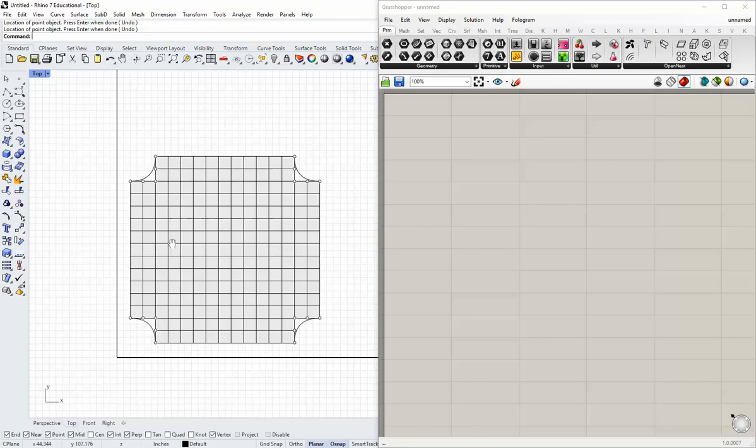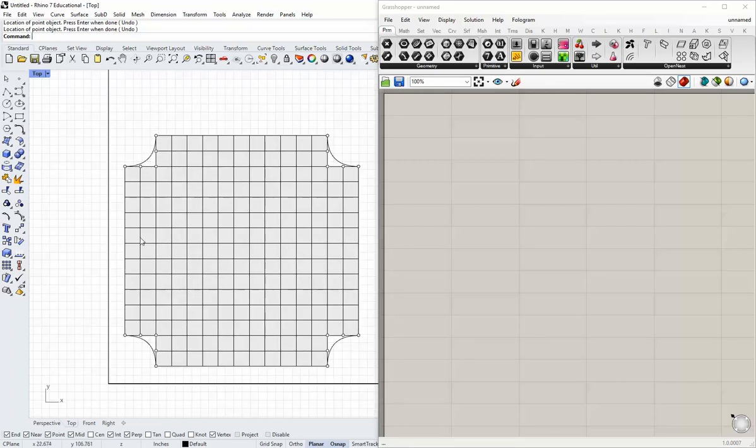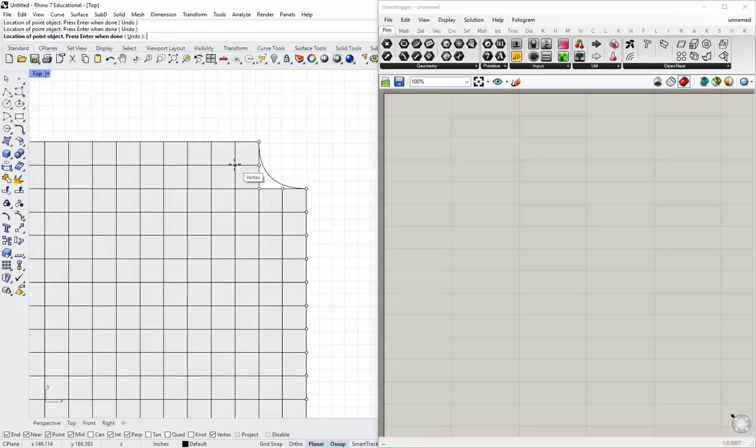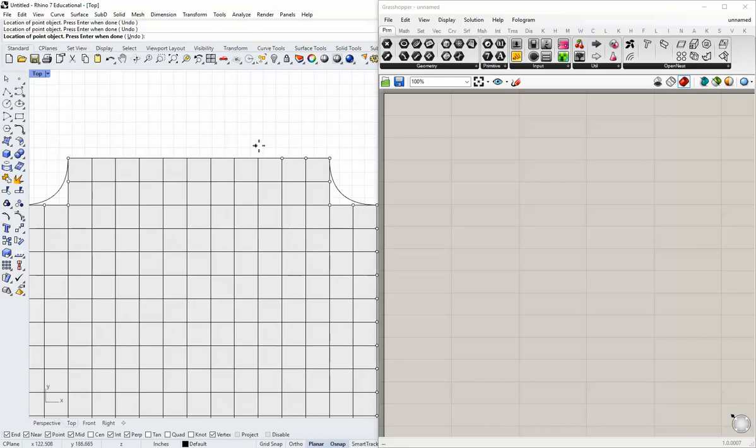And then lastly, you can do this in Grasshopper as well, but I just thought since it's not going to take too long, we can just kind of identify all the side points here, these outer mesh points. Just snap to each vertex. This is very, very important that the point rests at the exact vertex of the mesh. If it's a little bit off, you'll have a problem.